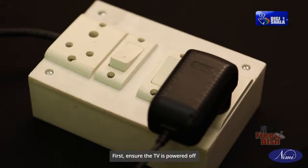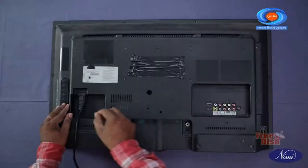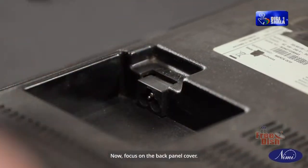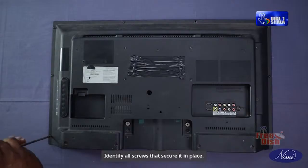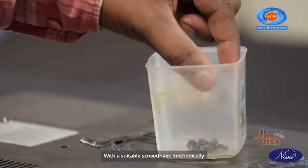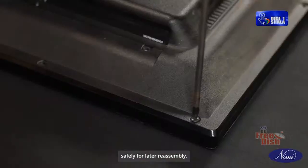First, ensure the TV is powered off and disconnected from all power sources. Carefully remove all connected cables. Now focus on the back panel cover. Identify all screws that secure it in place. With a suitable screwdriver, methodically unscrew each one, storing them safely for later reassembly.